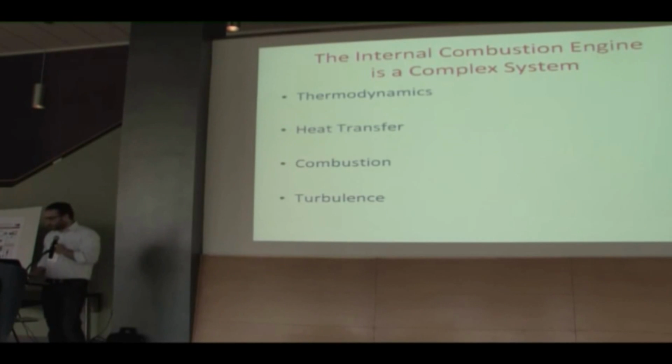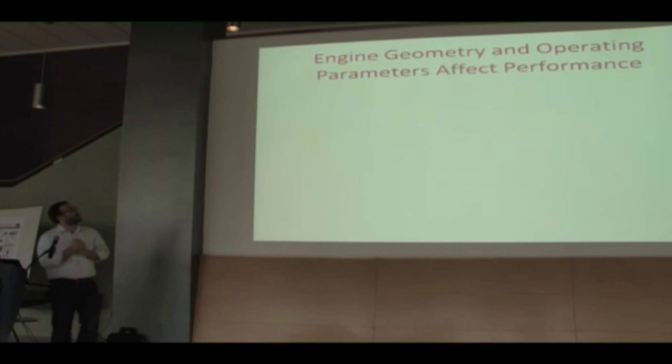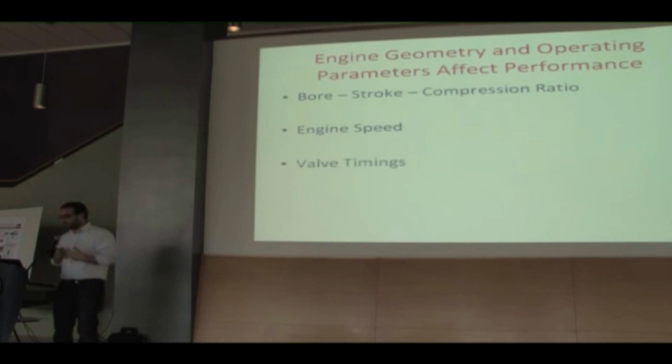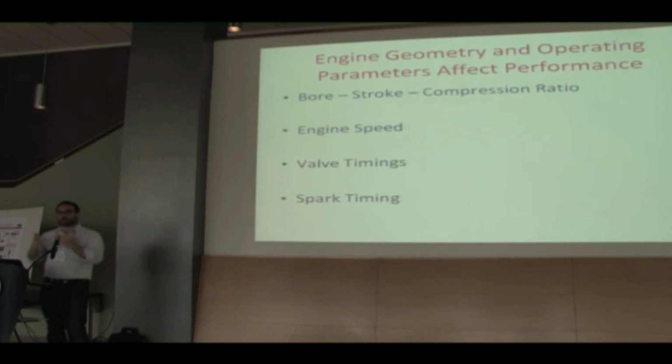And as such, immediately you see that you start talking about so many things, it's good to put them in practice. So the operation of an engine is affected by a lot of things. The geometry of the engine, how big the bore is, how far the piston moves, the stroke, as we call it, and so on. And also operating parameters. What is the engine speed? When does the valve open? When does the valve close? When is the spark plug fired? And so on.